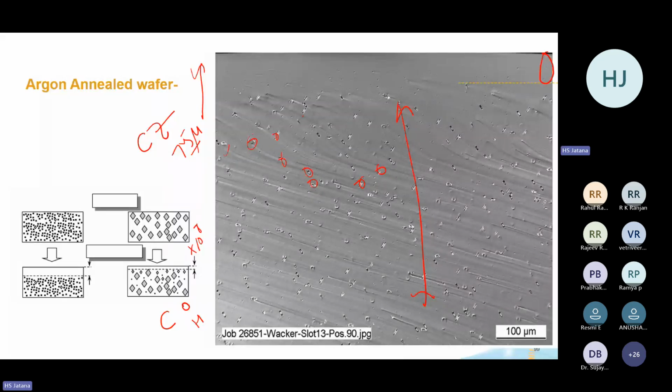temperatures. And besides, you have to hold the wafer by vacuum, so it should have some mechanical strength. An 8-inch diameter disc, if it is 5 micron or 10 micron thick, will not be able to take 1200 degrees centigrade. There will be bow and it will break. That is the reason why 725 micron thickness is there.